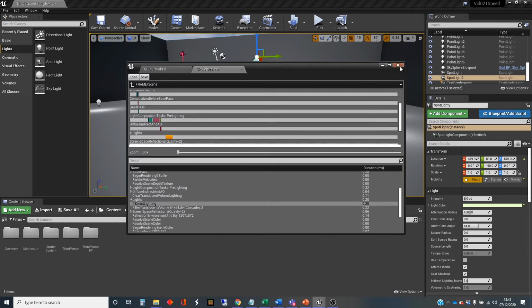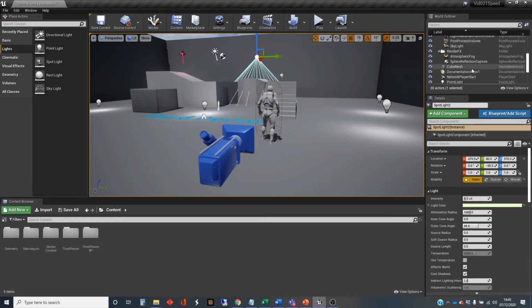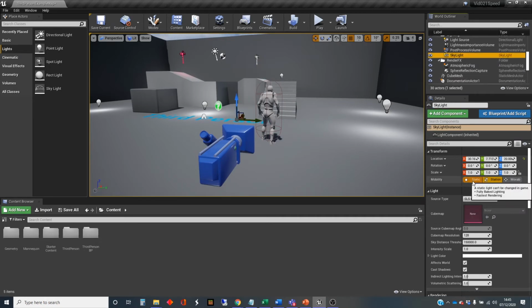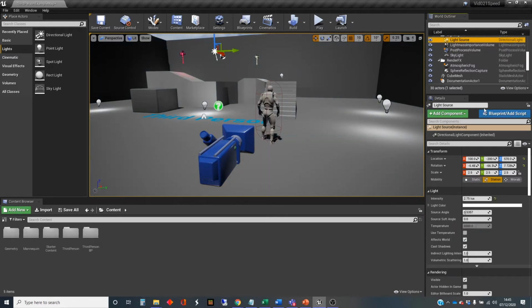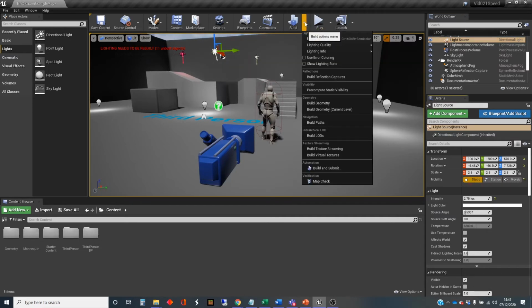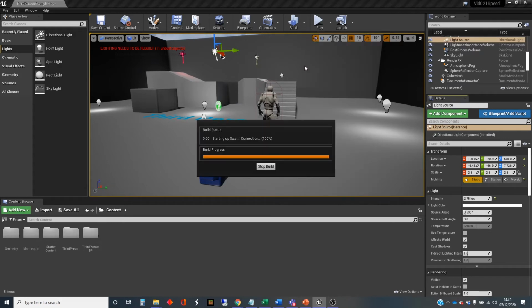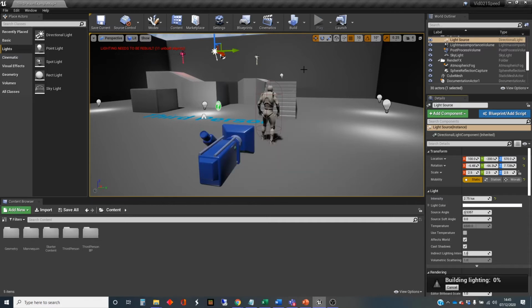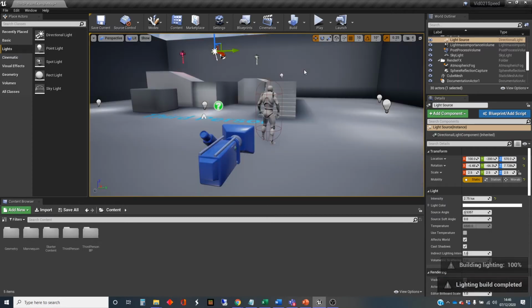And in fact, we can go even further with this because there are a couple of built-in lights in this third-person template, which is the skylight, if we're not going to make any changes to that, and usually we're not, and a directional light source. We're going to turn those both to static. Once again, we're going to build our lighting. Build lighting only. The preview is grayed a little bit, but this should go back to normal once we build the lights. There we go. It looks slightly different, but this is the way it is.